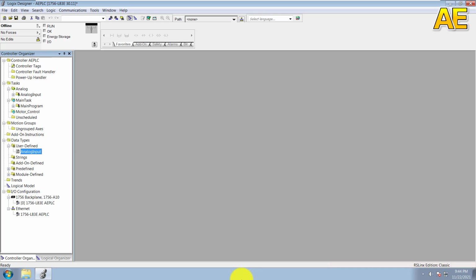Step 1. Is the local Ethernet/IP module for the network already in the I/O configuration? If no, then add the local Ethernet/IP module first. Find the local backplane in the I/O configuration folder of the controller organizer. Here, the 1756-A10 backplane. Right-click the local backplane and click New Module.